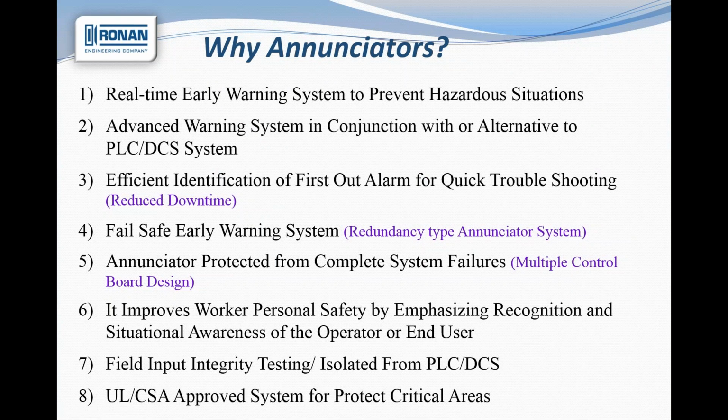So why in the world would somebody want to use an annunciator when they've got a good DCS and PLC system? Like I said before, it gives an early warning. It's independent from the system, so if your DCS or PLC went down, this is standalone. It is an efficient way to identify first alarms for troubleshooting.